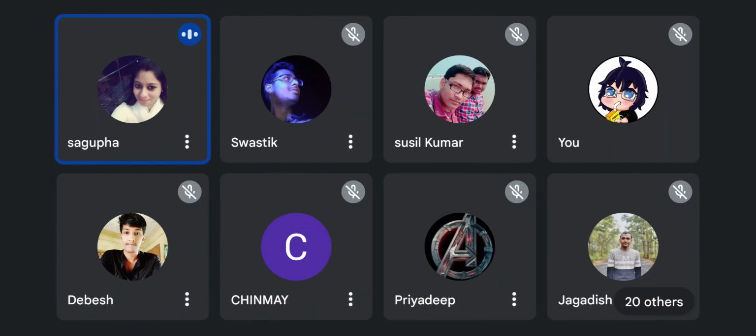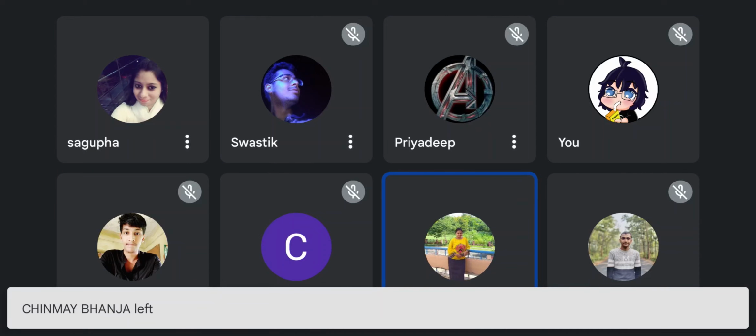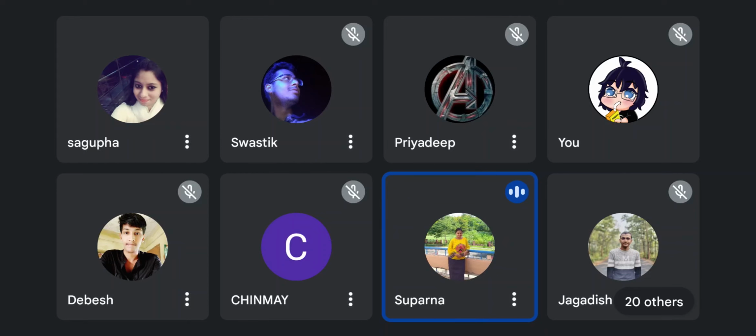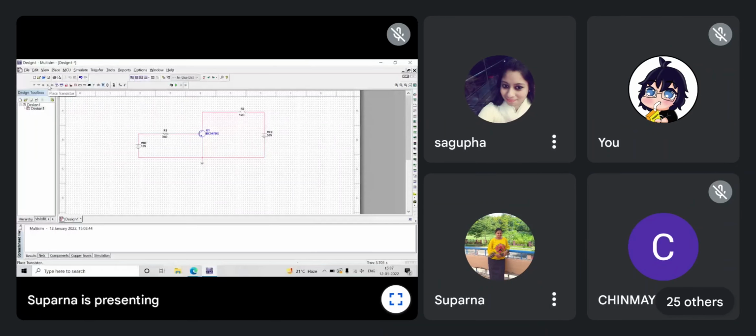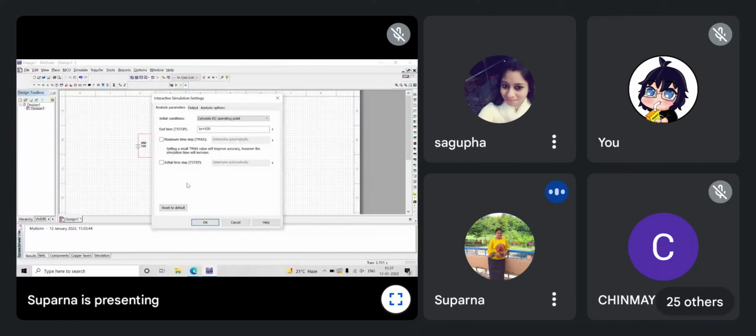Anyone else wants to show? Ma'am, I'm not getting my DC sweep. Can you please help me out with this? Yes, share your screen. When I'm clicking on interactive simulation settings, this window is coming. What should I do next? Okay, reset to default.